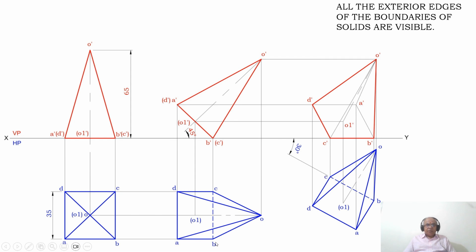Then by using the compass, you measure the distance from C to B of the second position top view. From C, you cut it on the 30 degree line, so you mark that point as B. Then by using the protractor with reference to C, with reference to this 30 degree line, you measure an angle of 90 degrees and draw a perpendicular to BC.